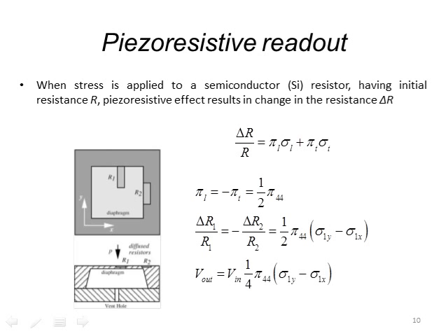Okay, in this case, we're going to assume that this is a plate. So the thickness of the diaphragm we can see on the lower diagram, where if we look at just the top part, we're going to have these thick regions on both the right and the left side, and in the center we have a thin diaphragm. So this thin diaphragm region corresponds to the light gray region in the top image. Now, when we get a pressure, this square diaphragm is going to bend, and it's going to have the gray deflection directly in the center of the square diaphragm.